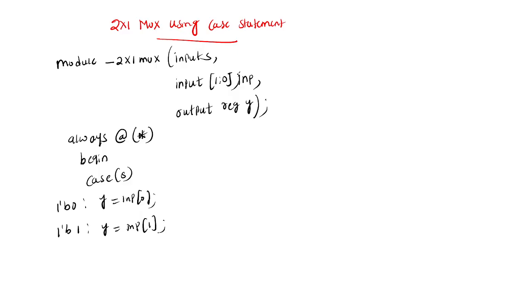Here in the case statement there is a default statement. Why this default statement, I will tell you. For every case statement you need to use a default. So y equal to 1'bx, end case, end begin, and end module.